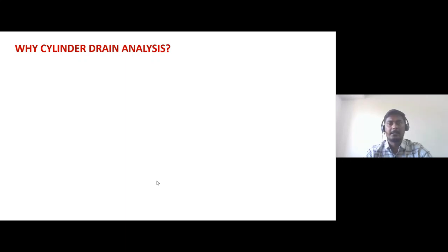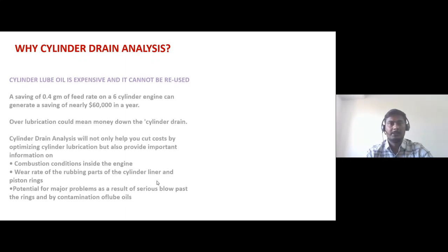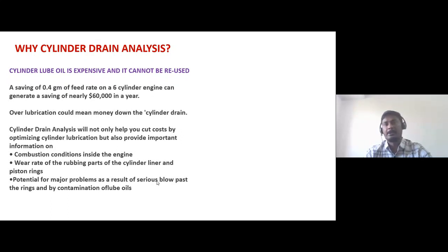Why is cylinder drain analysis required for ships? Cylinder oil is expensive and it cannot be reused. Once you spray the cylinder oil into the liners, you cannot use that cylinder oil again, because of all the deposits and blow-by combustion byproducts mixing into it. So it comes under the drain-down oil.